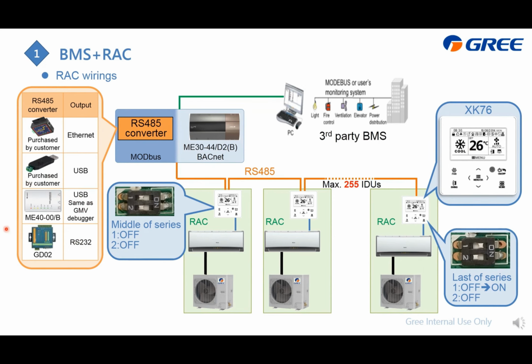On the other hand, as it is RS485, to ensure the communication, if this wire controller is located in the middle, there is no need to turn on the built-in resistor, which requires changing this built-in switch. Not turned on means all at off position, just like this. And if this wire controller is located at the last, you need to turn it on to ensure the communication, which the setting is just like this. Just change the first step from off to on.